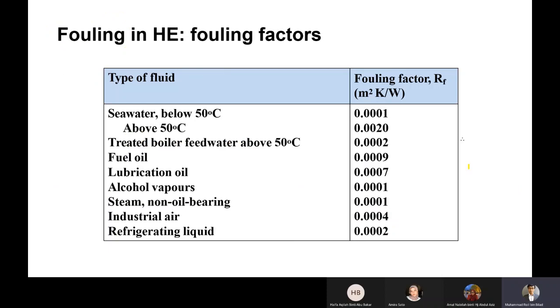Okay, typically the values, if you are dealing with seawater at this given temperature below 50, is around very small, 0.001 meter square Kelvin per watt. And then the highest here, I think, is when you're dealing with fuel oil.